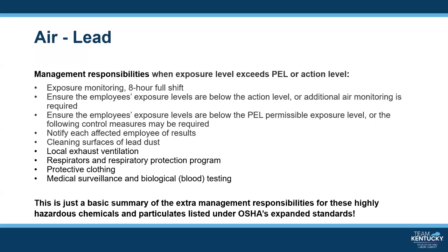Management must ensure the employee's exposure level is below the PEL, or that would require the following control measures. With the air sampling, the employer must notify each employee of the results of this testing. It would require cleaning of surfaces of lead dust. It would require local exhaust ventilation.